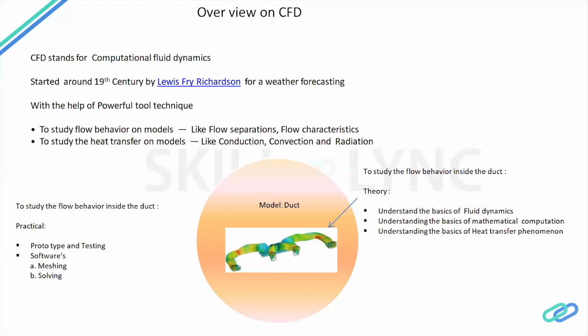That is why in the textbooks we read examples for the fluid dynamics part. But in a real scenario, each fluid has some viscosity, so we need to consider the viscosity characteristics of a fluid in a practical scenario. So we can modify Bernoulli's equation by incorporating the viscosity terms, which is called the Navier-Stokes equations. This Navier-Stokes equation along with your basic continuity equation leads to the basic equations of CFD. These basic equations are built into a lot of industrial application solvers.